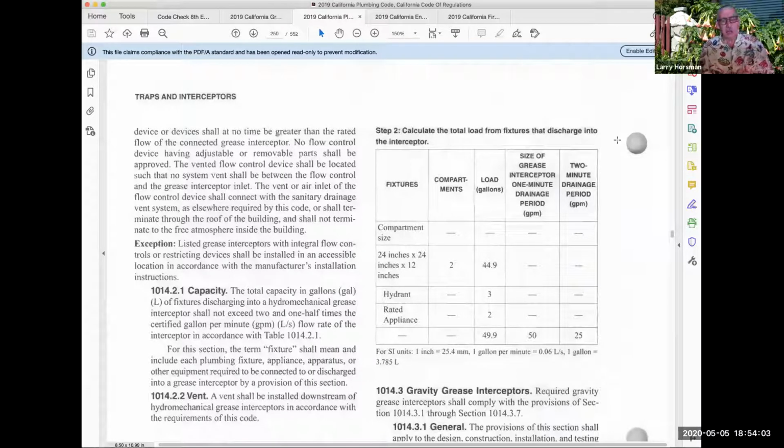You find the volume, take 3/4 of that, because if it's completely full and you put something in it, it's going to overflow. So they figure it's 3/4 full. And then the volume in cubic inches divided by 231 gives you the gallons, and the time gives you the gallons per minute.